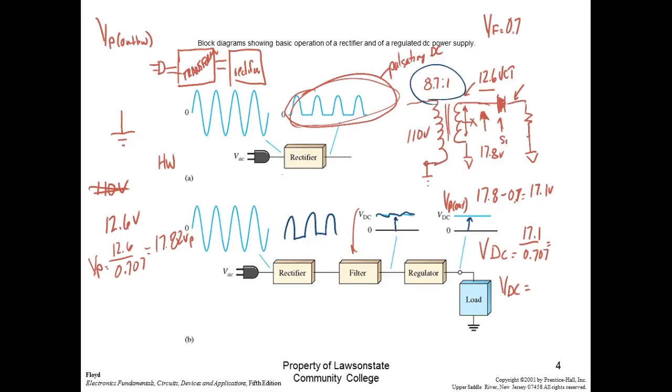So when they give you 12.6 volts, that 12.6 volts would be at 1 amp. So that's another reason we're getting more voltage out: this transformer is rated at 1 amp, and we're not nearly pulling 1 amp out of this. So now my transformers give me a little higher voltage than what I think, right? You understand? For 2 reasons. One reason is we're putting 120 volts in it, and the other reason is we're not loading it correctly. So yeah, they could regulate it with an electronic circuit, but then your power would probably cost you $2,000 or $3,000 a month instead of $100 something bucks.